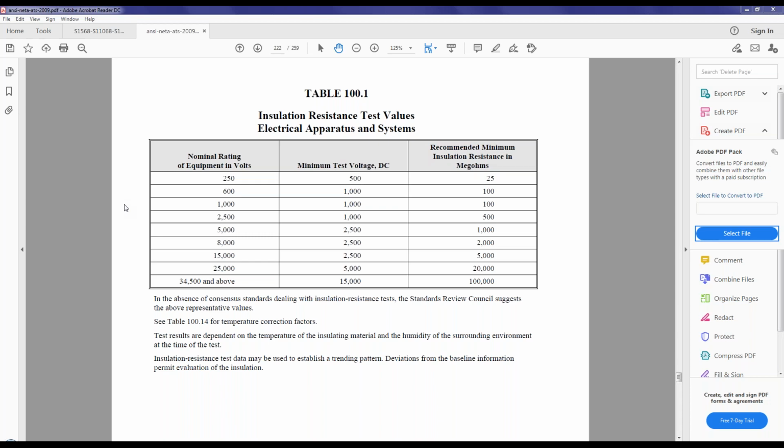When we perform an IR or PI test on a power transformer that has different voltage levels, such as the high voltage bushing and neutral bushing, do you recommend using the guard terminal, or just the neutral bushing? The good thing with the guard terminal, sir, is that it will eliminate any resistance that should not be included in the measurement.